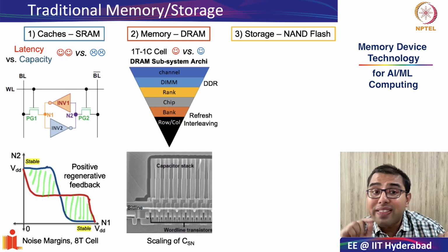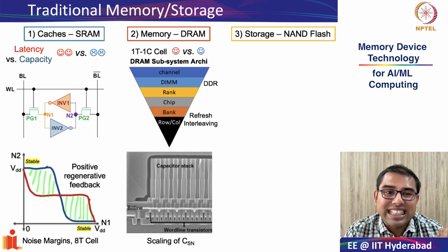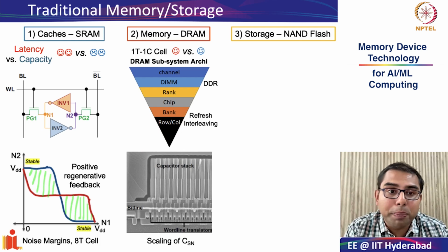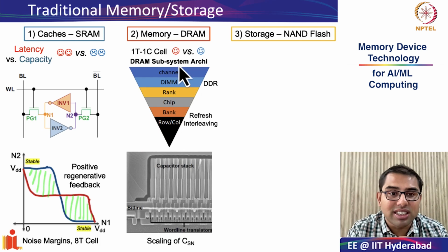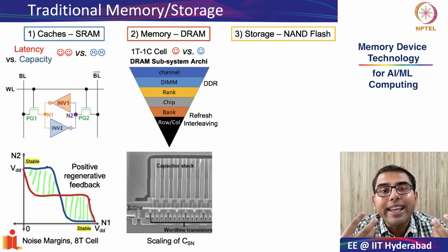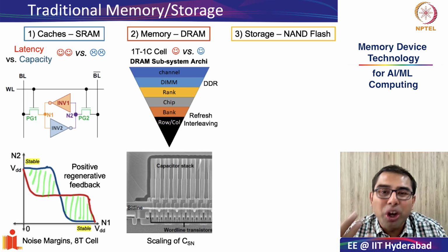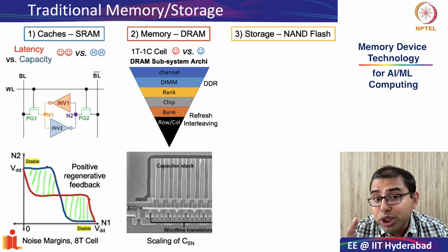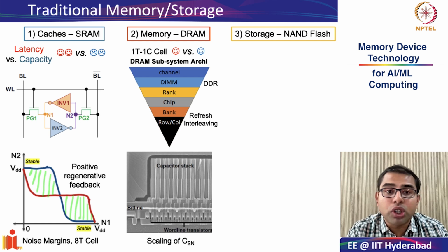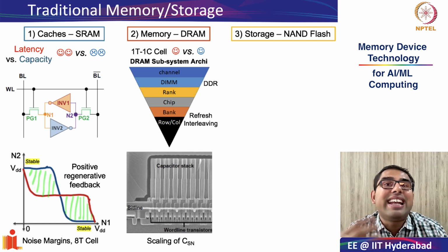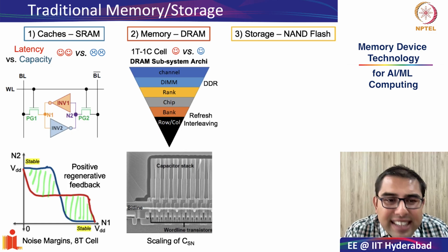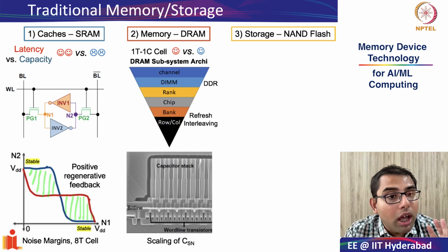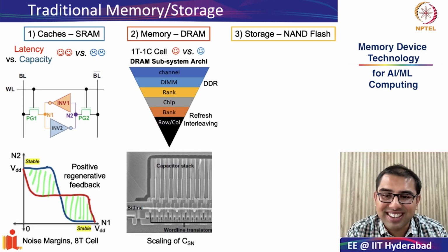However, we saw that beyond just the device, the DRAM subsystem architecture, which takes the form of this inverse pyramid, as you can see in your slides, something that we are familiar with, is what gave you these massive improvements in throughput, which helps us to somewhat circumvent the memory wall. Also, through very interesting concepts of dual data rate, refresh, and interleaving, you were able to somehow manage these throughput differences between the DRAM subsystem and your processor subsystem.